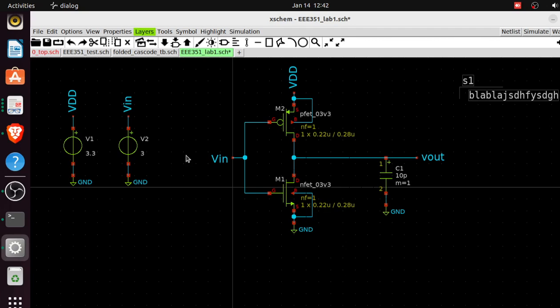But why did I just emphasize the sizing? That's the W over L ratio. Not only the W over L ratio do you as a designer have at your disposal, you also have the VGS, the gate voltage, to control. So actually you have just two things to control. The remaining parameters, the transconductance parameter, the threshold voltage, and the rest, are not in your control.